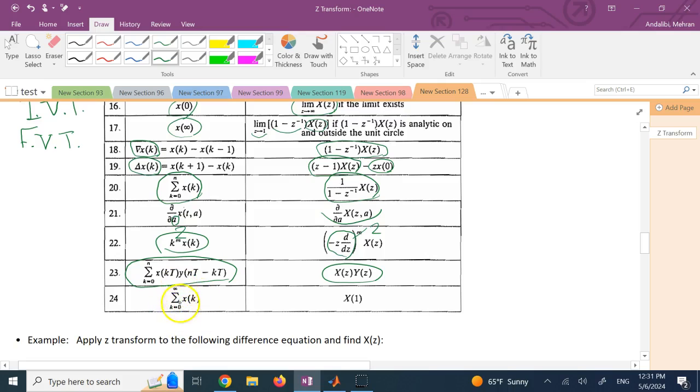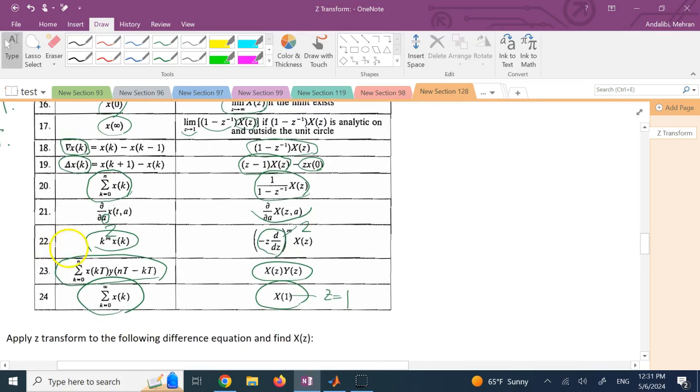And of course, it says that the value of the summation of a signal x(k), k from 0 to infinity, is the same as X(z) where you plug in z equal 1. So X(z) at z equal 1 is the summation of all terms in the series. For instance, let's apply it to the exponential term. This x(k) is e to the negative kt, or negative k in general. Then if you find X(z) for that, here you want the summation as k goes from 0 to infinity.